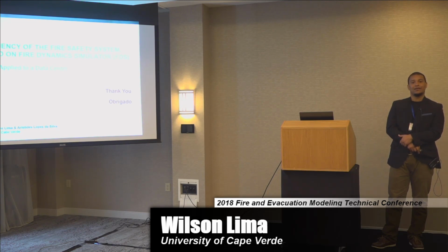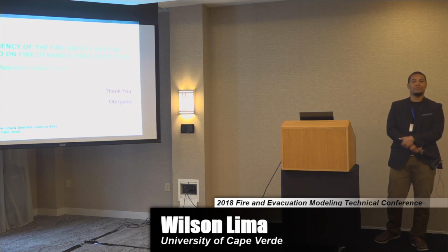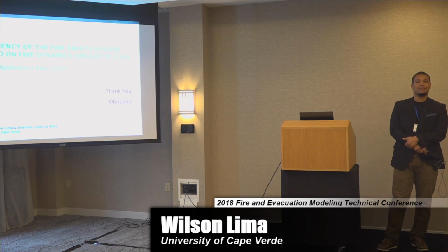FDS is going to conserve the enthalpy of the liquid when it evaporates into a gas. If you define inconsistent properties, that can result in instabilities, because FDS is going to do what you put as the inputs, and if those inputs are non-physical, a non-physical result can lead to an instability. So you have to make sure that the enthalpy of the liquid phase and the enthalpy of the gas phase are consistent with the heat of vaporization that you're defining. Otherwise, you're likely to get an instability.